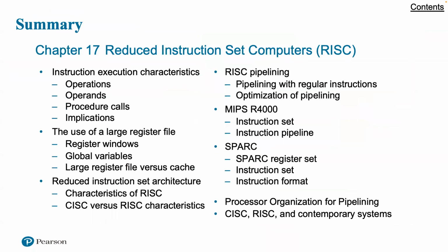Okay, well, we covered a lot of detail here. Hopefully you're getting the big picture of what we're trying to accomplish. We're trying to get more specific in terms of what are the advantages of processors. And so for this lecture, we were looking at the pros and a little bit of the cons for reduced instruction set computers, having everything the same length instead of variable length for the instruction set, and looking at some of the design options.